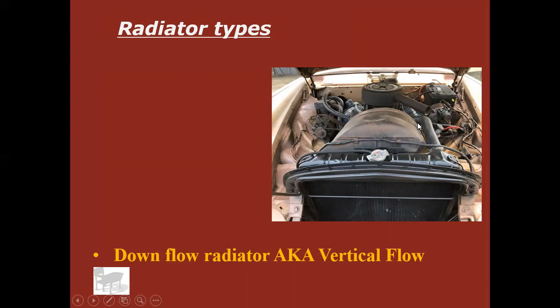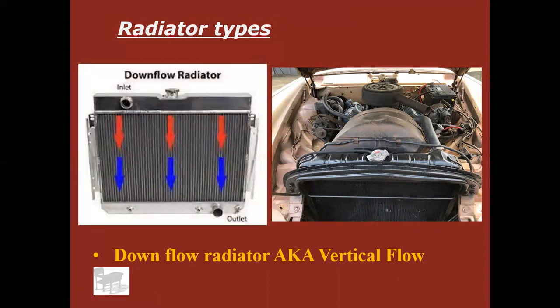So the coolant comes in from the water pump at the top, fills this kind of tank at the top of the radiator, and then it just falls down through these tiny little cavities or fins down in the radiator and gets to the bottom, goes back into the engine, process repeats. Okay, downflow radiator. There's another way of looking at it. The heat, it's hot at the top, cool at the bottom, or cooler at the bottom. Okay, comes in here, falls down, goes back in the engine there.